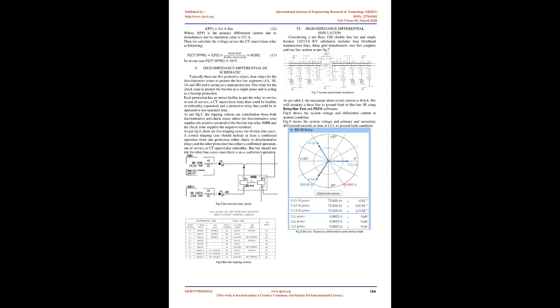D. Design of shunt resistors R_SH. Many busbar high impedance differential protection schemes were designed without shunt resistors, but some protective relay maloperations have been recorded due to differential current produced by the following cases. 1. In case of heavy current external faults where there is no CT saturation, but due to CT error that is not equal for all the used CTs, a differential current might be produced. 2. In case of switching or sudden tripping of any heavy current bay connected to the busbar. That leads protection engineers to set a minimum sensitivity current limit that can operate the protective relay.